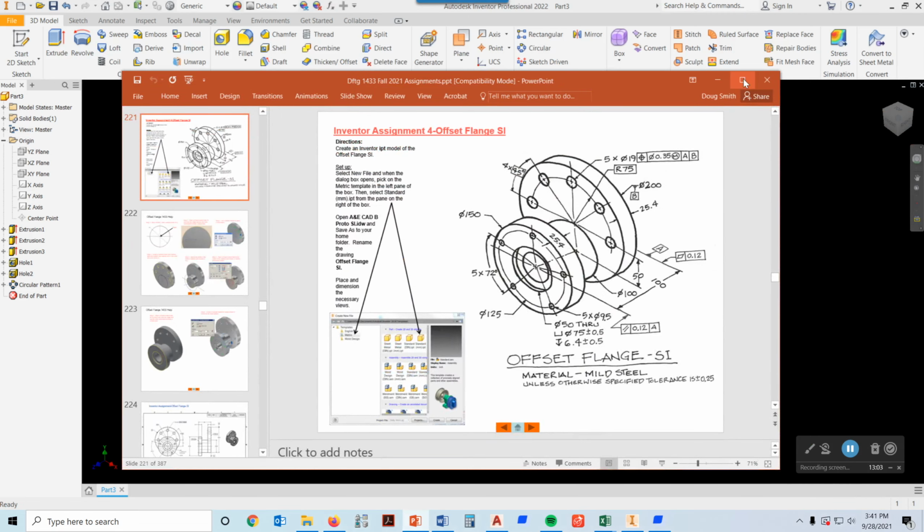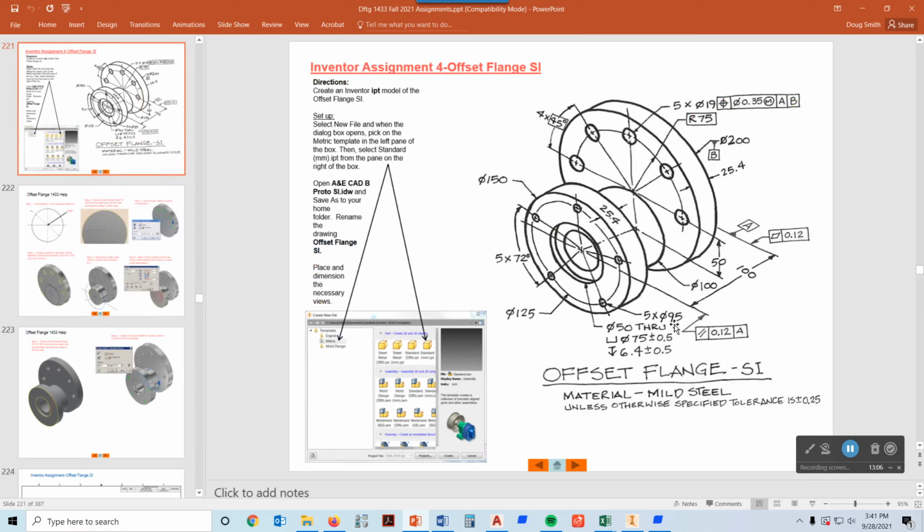And those holes are, let's see, 9.5 millimeters in diameter. There are 5 of those, and they are placed around a bolt pattern that has a diameter of 125 millimeters. And if I look at these holes, I would see that none of these 4 holes that I'm pointing at here lie on a horizontal or vertical axes, but this hole right up here at the top does lie on the y-axis, directly above the center mark right there. So I'm going to build this one first, and then I'm going to pattern the rest of them using the dimensions that I have in here.